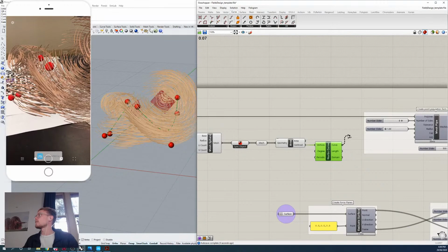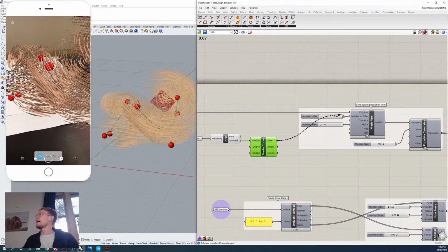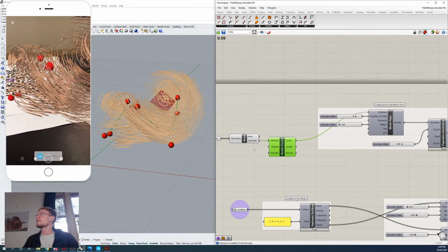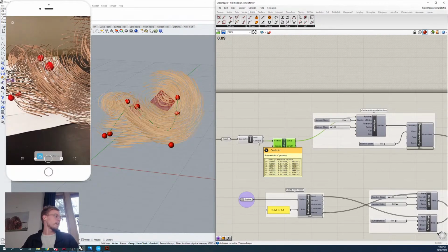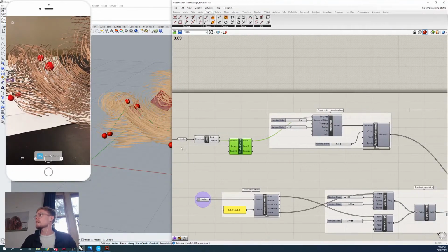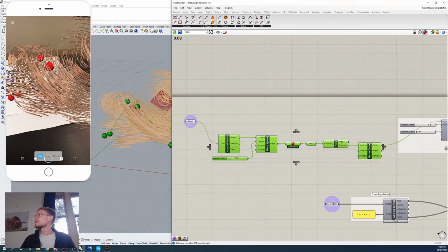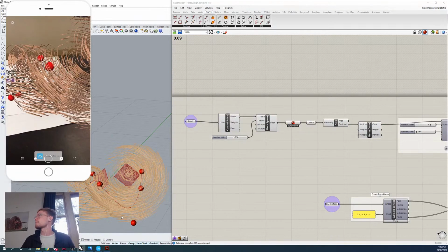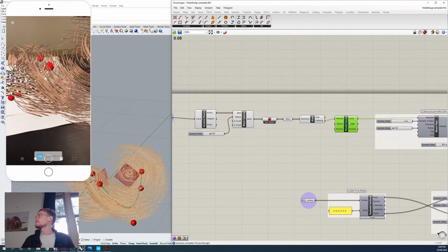And then I'm going to plug all these NURBS curves into the mesh pipe. So we're going to override this polylines input here like that. Nothing will change immediately. You'll get a very slight change because the curve's a little bit different, but you'll still get a very similar kind of aggregation. So I'll make that a little bit more obvious on my screen so everyone can make sure they've got that correct. So it all looks the same. So plug that into polylines.